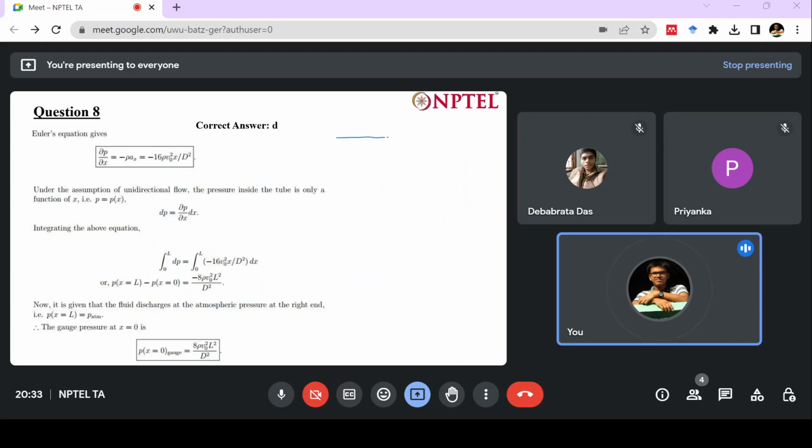So when there is a free surface, we denote it like this. Then there are no stresses that are exchanged between these two surfaces. So shear stresses are zero. So whatever velocity profiles we will have, if this direction is y, then del u del y will be zero. And the pressure here and pressure here will be the same, constant. The pressure outside the interface is equal to the pressure inside the interface.